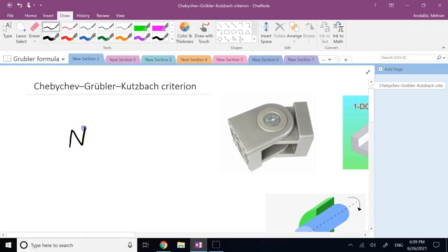So, right, you have n rigid bodies, one of them is the ground, then the total degree of freedom for all of these n members is (n minus 1) times 6. Why minus 1 again? Because one of them is the ground link. So this is the overall degree of freedom, DOF, of the system if there is no constraint.